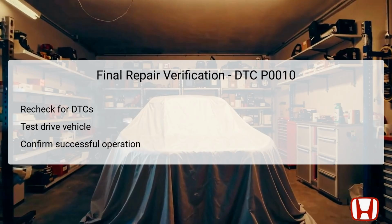After completing repairs related to DTC P0010, it's crucial to verify the effectiveness of those repairs. Begin by rechecking for any stored diagnostic trouble codes using the HDS. Conducting a test drive is also essential, allowing the technician to monitor the vehicle under various conditions to confirm that any initial symptoms are resolved.